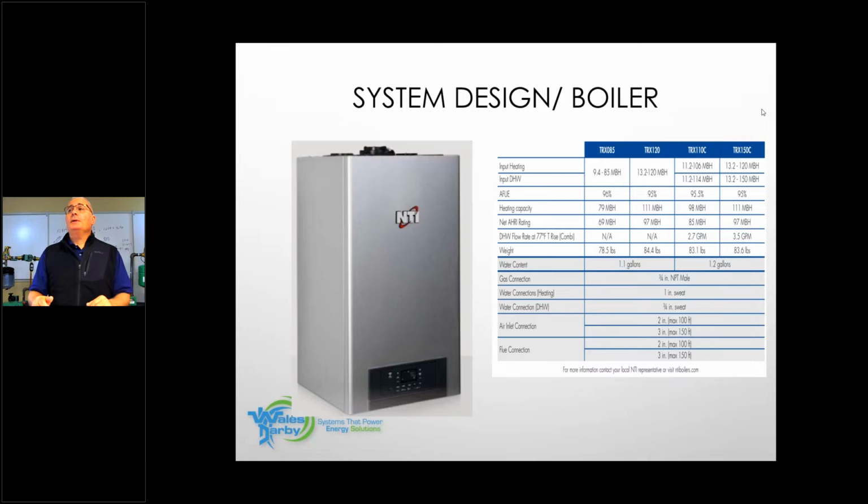If I set this boiler up with the boost function, that means if it takes, I believe, more than 10 minutes to hit my room set point, the boiler is going to boost up the water temperature automatically. Then the next call for heat, that will be our target for what we're looking at next time. So that boost function enables the boiler to function the way it's supposed to function, and the homeowners will be comfortable. So use that to your advantage. It's a big deal.